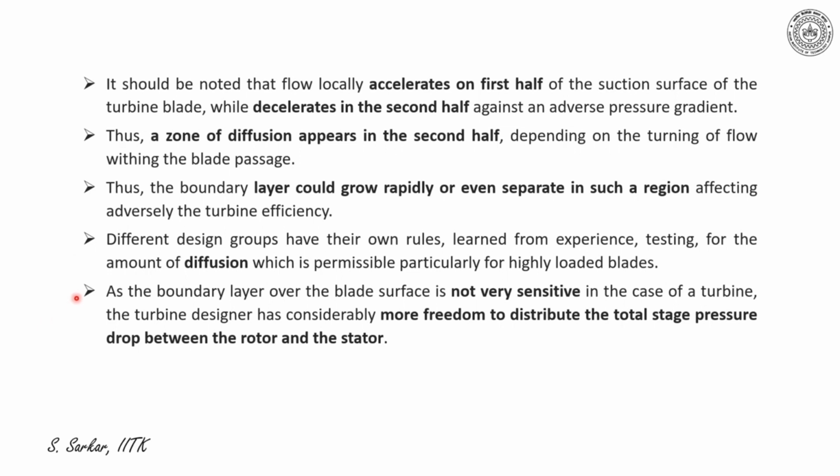Overall, I can say that the boundary layer on the blade surfaces is not very sensitive in the case of a turbine, and the designer here has more freedom in distributing the total stage pressure between the rotor and the stator.